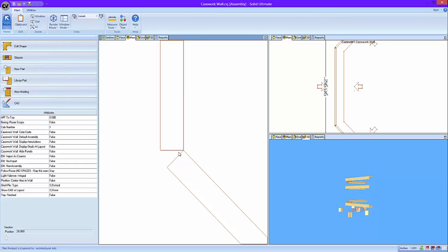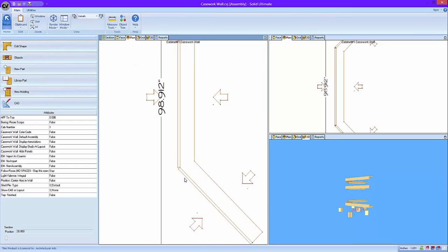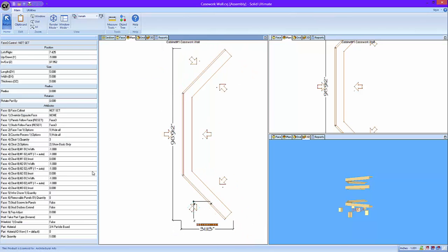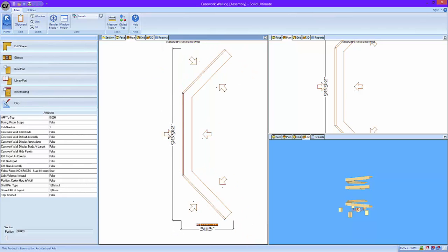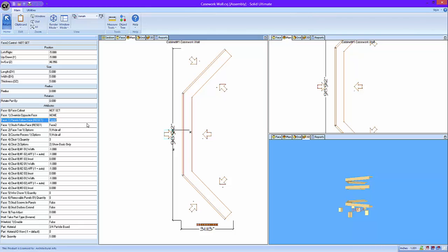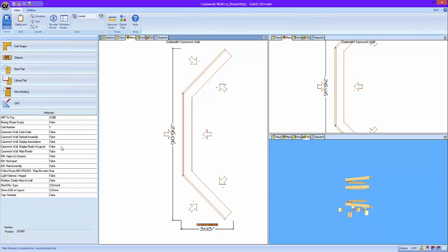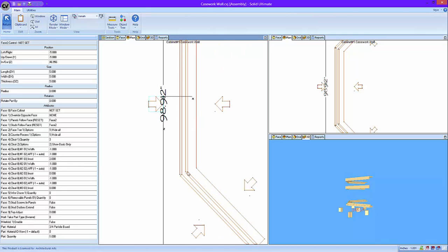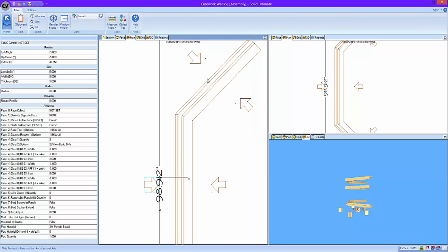And you can see it's sized them properly so that they won't conflict with one another. Actually, this is face 2. Let's tell this to follow so that we can modify everything at the same time. If I inset one of these, you'll see their sizes are adjusted so that they still don't conflict.